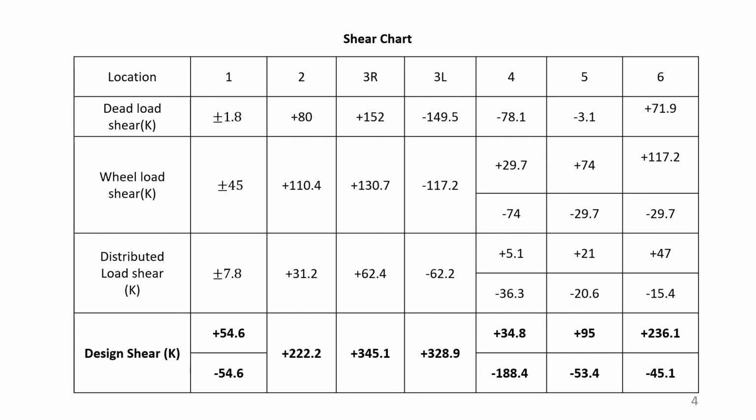There is nothing more to explain here. We take the previous charts, the dead load shear chart, wheel load shear chart, and distributed load shear chart, and you will see the plus minus signs and bring them here, and after adding plus with plus and minus with minus, we will see which one is bigger, the plus one or the minus one.